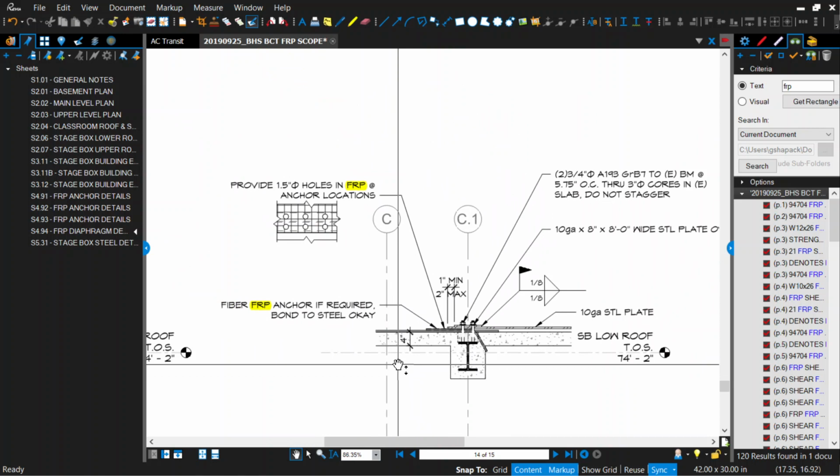The way we've done the calculations in the past is taking the shear equations from ACI 440.2. But what we're thinking would be better is to use shear friction calculations, because what we're showing is transfer between the wall on the top and the beam in the middle. That's where we have the joint, where the shear force wants to cross, with added shear strength.